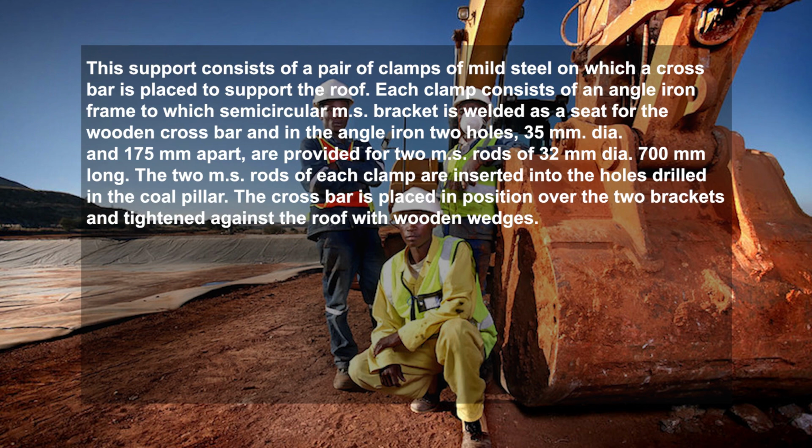and in the angle iron two holes 35 mm dia and 175 mm apart are provided for two rods of 32 mm dia and 700 mm long. The two MS rods of each clamp are inserted into the hole drilled in the coal pillar. The crossbar is placed in position over the two brackets and tightened against the roof with a wooden wedge.